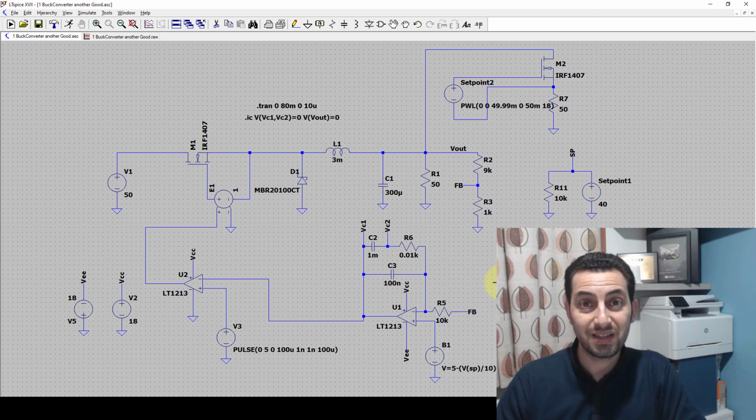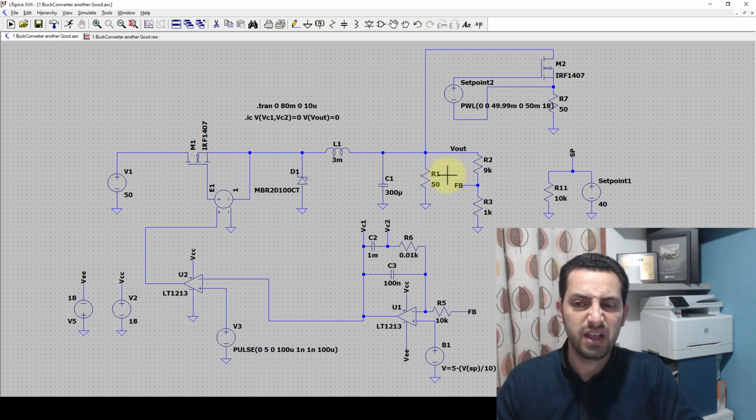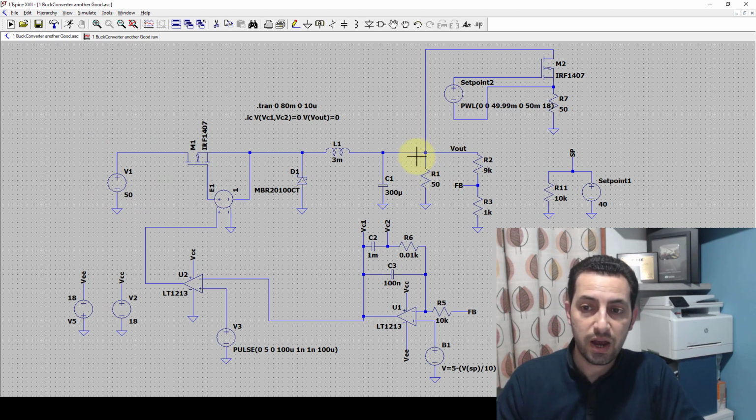Usually when you look at a closed loop system, they have this form of feedback network or compensation network to be considering the feedback into the PWM generation and make a regulation. I have this buck converter here. The input is 50 volt and the output is different from 0 to 50. The output load is 50 ohm here. And at the same point here, I considered another load, but that load will be engaged and connected to the system at 50 millisecond simulation time.